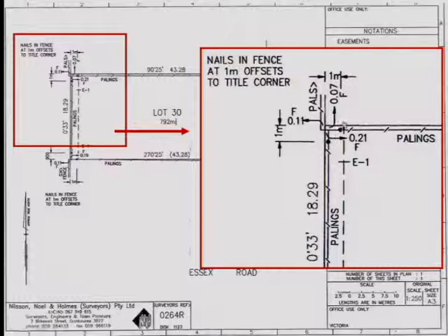You can see in this case, the fence is 70 millimetres inside the property. On that side here, it's 110 millimetres inside the property. So the legal boundary doesn't match the actual conditions of the site. Okay? Now that's, for an architect, really critical, because you can't have a contractor going out and measuring the building from the fence, because you've dimensioned it from the legal boundary. So to establish the relationship of the legal boundary to the actual boundary is really critical.